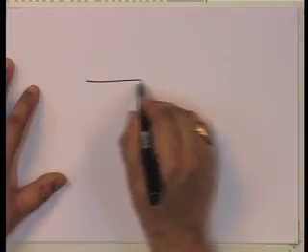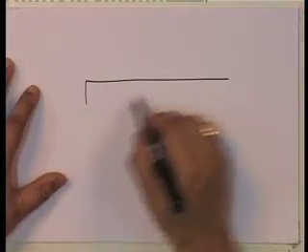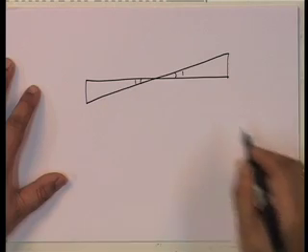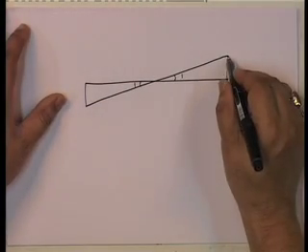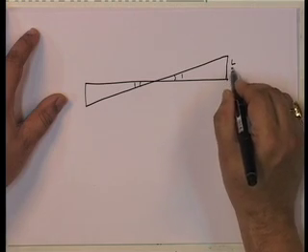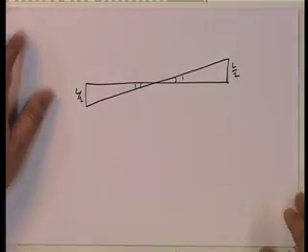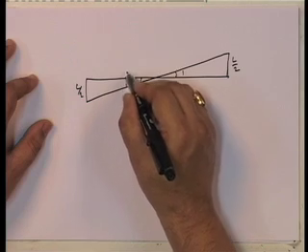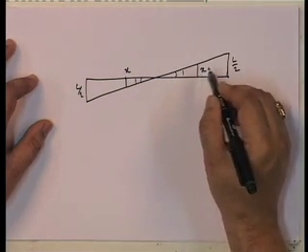So, now let us see if I can use the equations that I have used. I am only going to find out the k star, because everything else is again the same. So, let us look at what this is. This is a situation where xi is the one where you give unit displacement corresponding to the degree of freedom, and you find out the corresponding values. The corresponding values over here are L by 2, L by 2, and here this is going to be equal to x, and this is going to be equal to x.